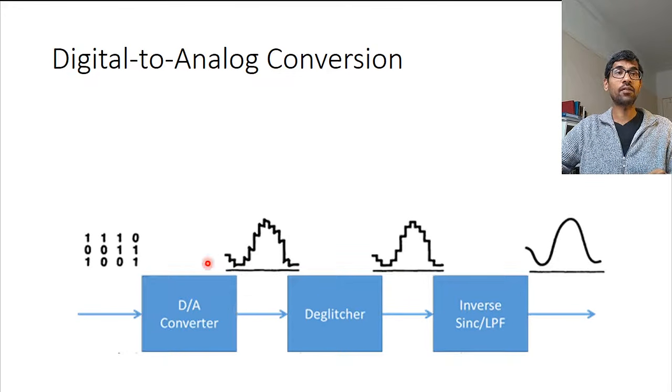What usually happens is when you use digital to analog converters, you would see in the later videos in this lecture that it uses a lot of switches, and using switches introduces what are called glitches in the signal. So you can see that these values in some places are not really constant. They go high and then go low, right? So you don't want these changing signals.